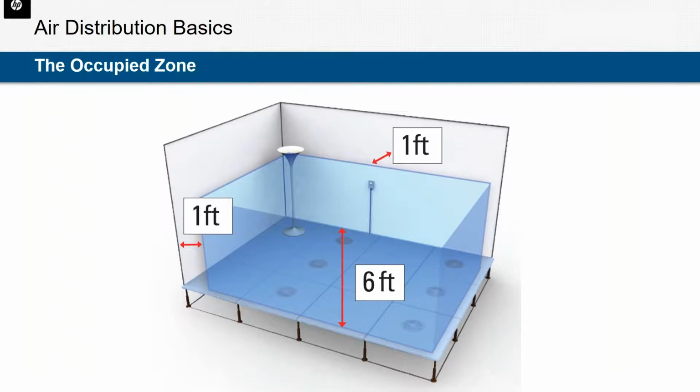If you look at ASHRAE standards, it's typically also 3 feet off of exterior walls. Outside of this boundary, we just generally wouldn't expect occupants to be there long term. Very rarely do people stand flush against a wall, and unless someone's on a ladder, rarely are they standing long term above 6 feet above the floor.